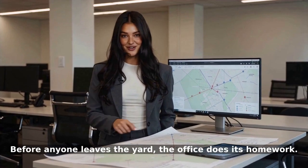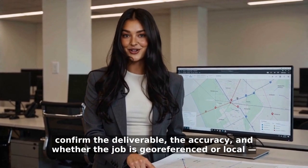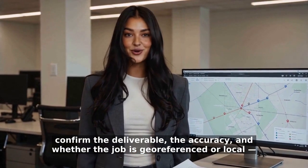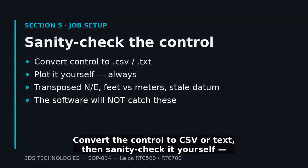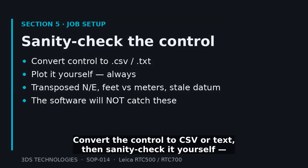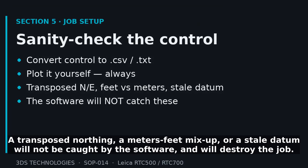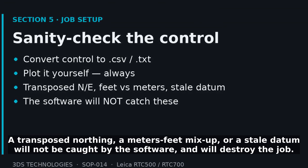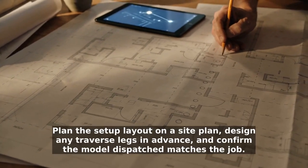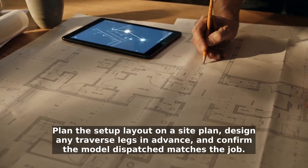Before anyone leaves the yard, the office does its homework. First, confirm the deliverable, the accuracy, and whether the job is georeferenced or local, in writing. Convert the control to CSV or text, then sanity check it yourself. Plot it. A transposed northing, a meters-feet mix-up, or a stale datum will not be caught by the software and will destroy the job. Plan the setup layout on a site plan, design any traverse legs in advance, and confirm the model dispatched matches the job.